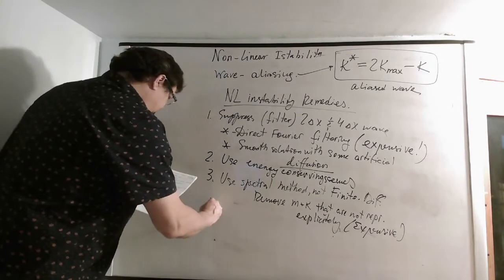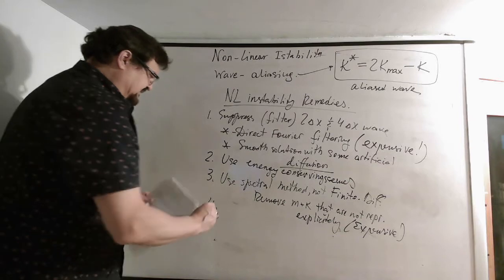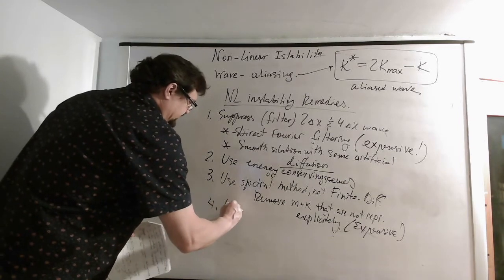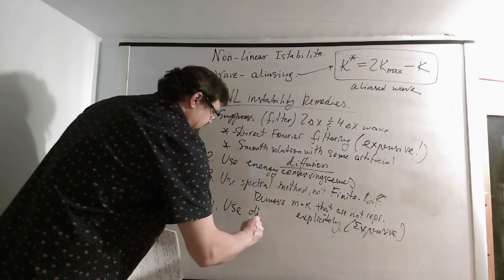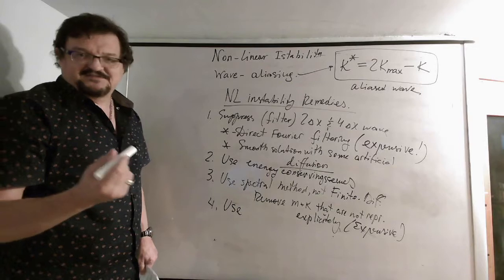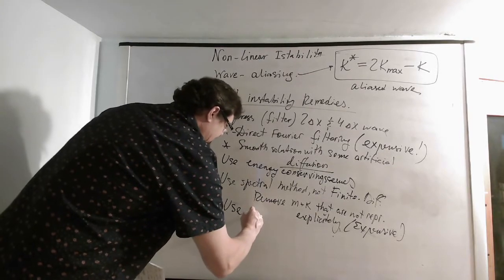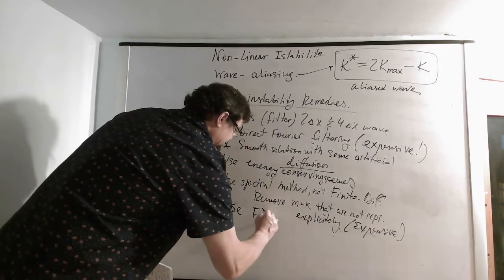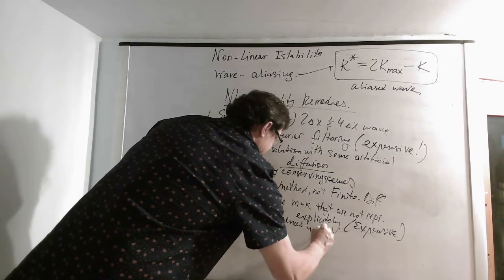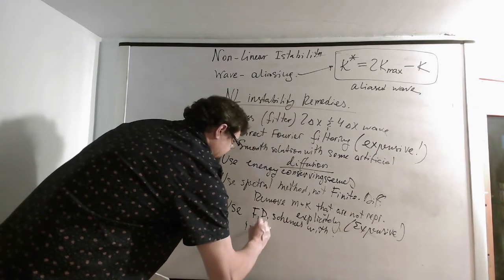And fourth, use dissipative schemes. Use finite difference schemes with numerical diffusion in them, with implicit diffusion.